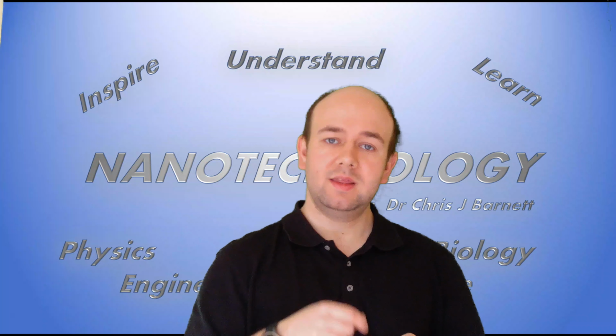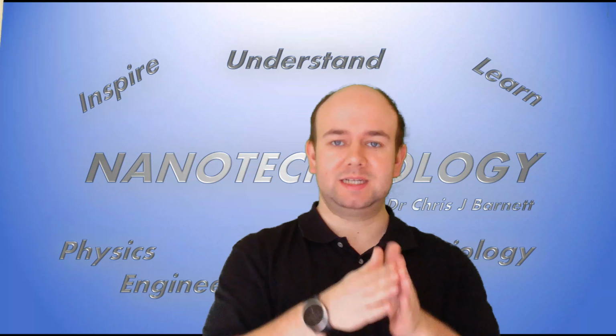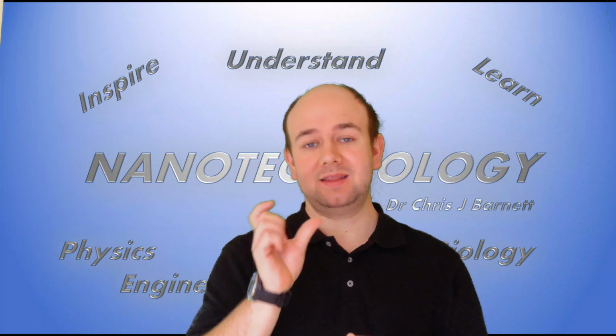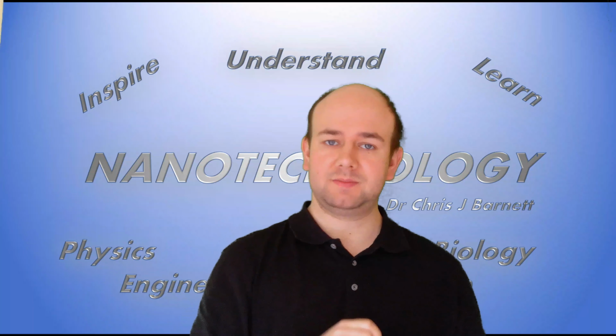So what's happening in the carbon nanotubes is, because they are tubular in shape, so they have a hole in the middle, when the catalyst is smaller than the diameter of that carbon nanotube, the electrons try to flow in, and then they have to push out towards the actual walls of the nanotube and to the extremes of it. So you get the electrons having to, instead of just moving down the tube in the direction of the voltage, having to spread out. And this is what's causing this current crowding. They're getting caught up as they move outwards.